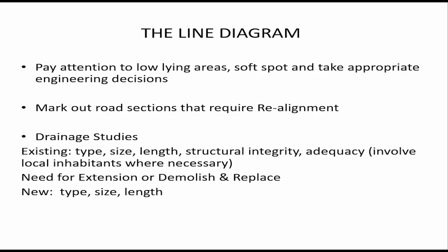And here too, I stated earlier on that on projects, you need to involve all stakeholders. So here, if necessary, you involve the local inhabitants. So when it rains, how does here look? Does it flood? Sometimes they'll tell you that you see this tree, when it rains, the tree is almost buried. And here too, it's always flooding when it rains. You need to get that information too from the local inhabitants.